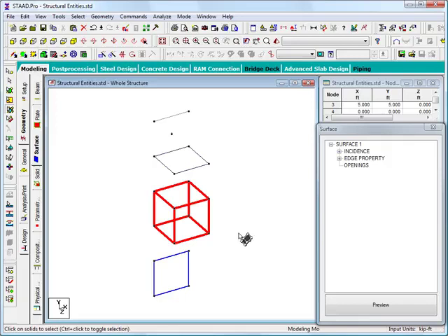They're useful for solving things that involve stress distributions in relatively thick structures like concrete dams or soil and rock strata. In their basic form, solid elements consist of 8 nodes, but they do have the ability to be degenerated into various forms by collapsing one node onto another, so that they can take on different forms that have between 5 and 7 nodes.